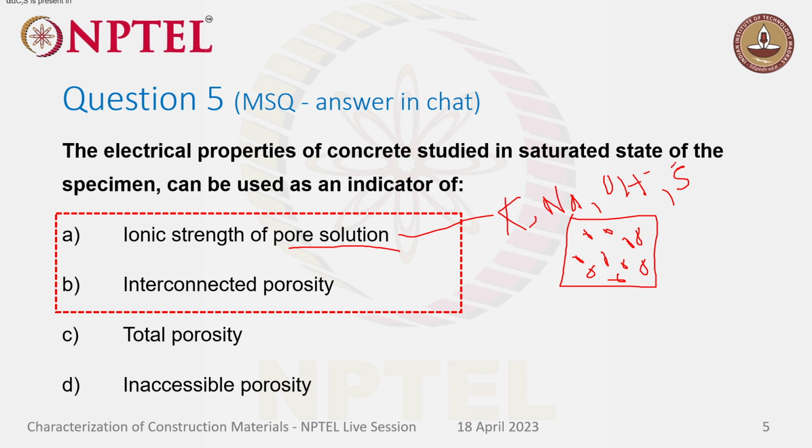I'm just putting a cap since it's cement chemistry. That S should not be Si, meaning silica, but in cement chemistry notation we use S for silica, so I just put a cap here. So there can be sulfur ions, and silica and aluminum ions can also be there. Since they are very, very reactive when we compare, they might have formed CSH like that.